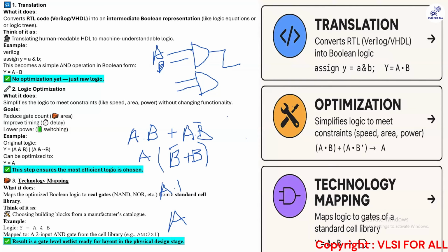The cell was intended to receive 0.67 volt, but since there were a lot of drops, whether due to high density cells switching at the same time, or due to resistance because metal layers used were on lower layers. That is a completely different theory subject. But let's say that instead of 0.67 volt, it got 0.6 volt.